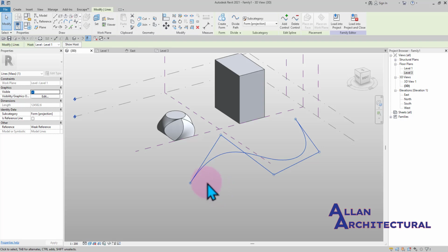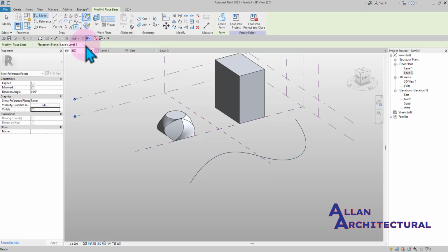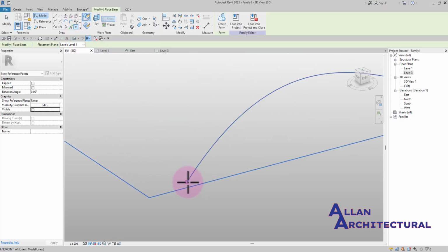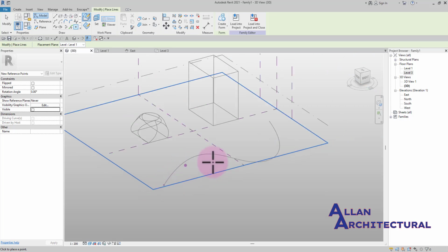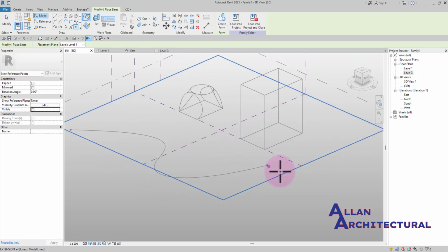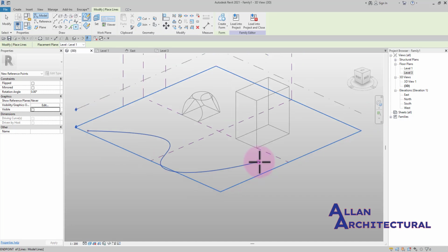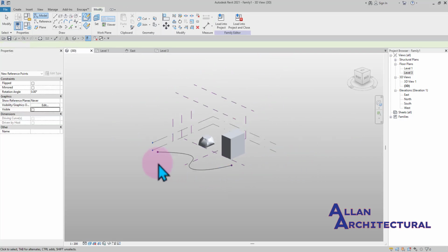So after creating the spline in there, what you'd want to do is click on this point element, and then just come in here, and you can drop one point element here, and then you can decide to drop one here. Now the reason why I'm going to drop one here is maybe I would want a different profile on the edges, and then I would want those profiles to blend together with this. But if, let's say, I'm just going to use a single profile, let's say a square, which is going to run in this shape, then I don't need to put a point also here, but I'm going to put a point here because I want two different profiles. All right, so this is perfect.